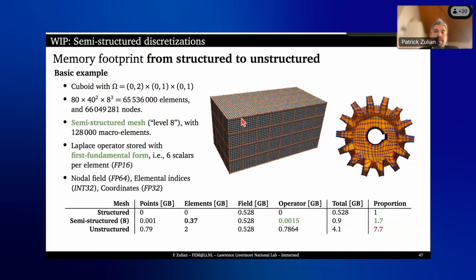So even for a mesh like this, if you're building a preconditioner, then you can sample the Jacobian of this element, for example in the middle, and have a very bad geometric approximation, but still be able to use it as a preconditioner. This is what I'm doing actually for this type of mesh. I assume these elements are affine, so then I can pre-compute certain stuff. And what I haven't done yet, but should be quite easy with some code generation, is to go for larger elements and generate some stencil operators. Then you can optimize the way you access the memory here. You can avoid, to a certain degree, atomic adds and all this stuff on the GPU.